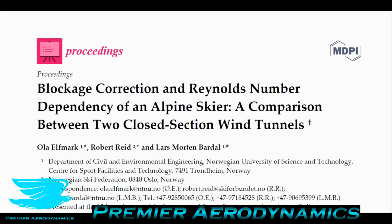And then that means that in order for it to go through this reduced area, it needs to speed up due to continuity. The continuity equation tells us that, particularly at low speeds, so with Mach numbers below 0.3, which is the general rule of thumb for when air is not compressible, there's only really one way for flow to go through a smaller area, which is to go faster. So if you have, let's say, 1 cubic meter coming through with an area of 1 meter squared, for it to go through 0.1 meter squared, it has to speed up by a factor of 10.